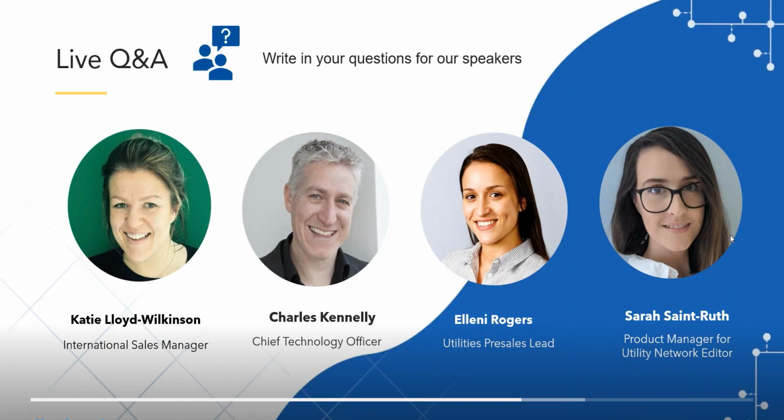And if I could just expand slightly on that, we have full support for branch versioning and different ways of interacting with it. But I would ask you all to think about when you're using versioning and how you're using it, because today quite often we use versioning because that's how we work. But you don't necessarily need to use it in all ways. If you're able to validate all the time and you're able to control the rules against your data, then some of the reasons you used versioning for in the past might not be there. So just consider that, because it can simplify things for the users. But we do support the full version workflows as well.